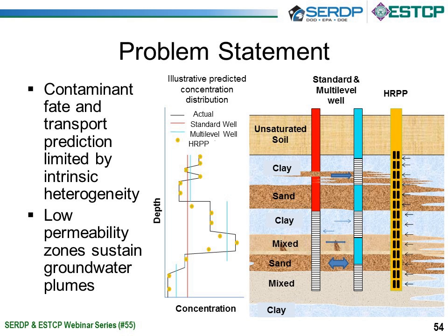So the problem we're really trying to focus on is the problem of heterogeneity in contaminated sites, particularly chlorinated sites. And so traditionally, wells have been used to monitor concentrations, biogeochemical conditions, microbial populations, although there are certainly many other tools available. But regardless, almost all the other technologies are dependent, at least to some extent, on the hydraulic conductivity. How well does water flow through each formation?